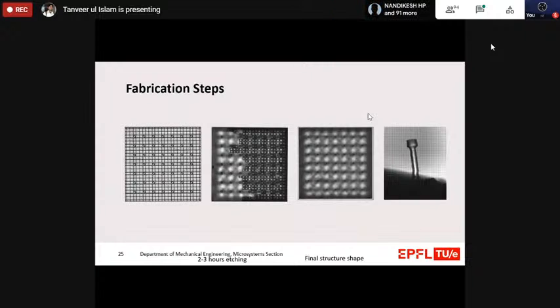That's a good question. Like I mentioned, when we want to fabricate something that has a three-dimensional shape, the laser has to penetrate through the material so that we can focus the laser spot, or the focal point, at different locations inside the material. That way the material has to be transparent, and that's why glass is used, because it's highly transparent. Along with that, it modifies the material in a certain way that could later be etched in a chemical bath. So right now we can only use glass material for making these structures.